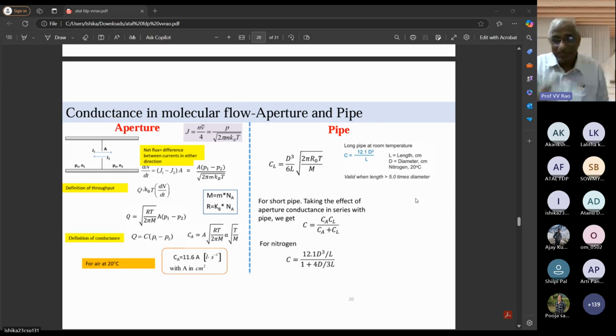They will start opening up at 10, 100, only up to 200 torr. If you are making 10 torr, you have already removed 99%. See, 100 torr means, sir, 100 millibar, let us say. 1000 millibar is the atmosphere. 90% of the gas has been removed, but no application excepting train stopping or some vacuum cleaner or something. But below that, 90 to 99, evaporating water, that is for squash, fruit juice manufacturing, or chemical industry where distillation is going on. Some mundane industries have started, up to 1 torr.